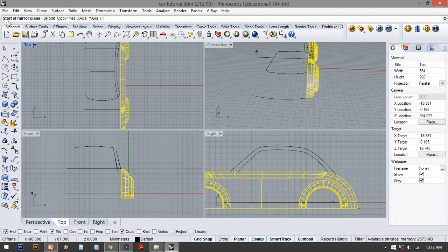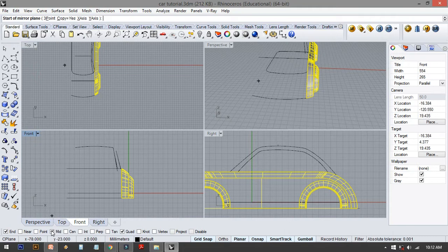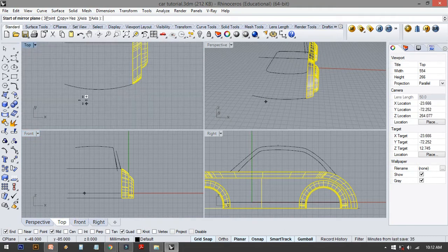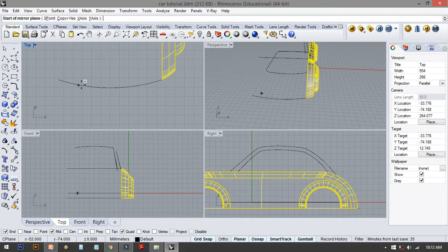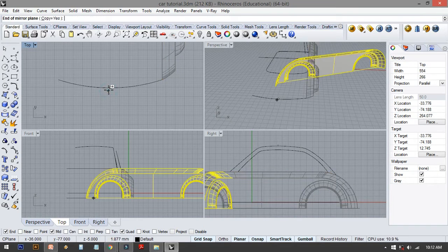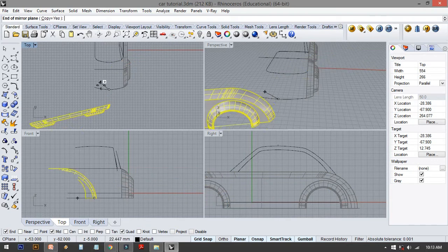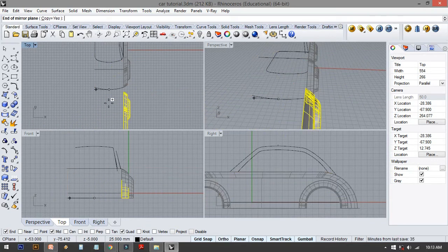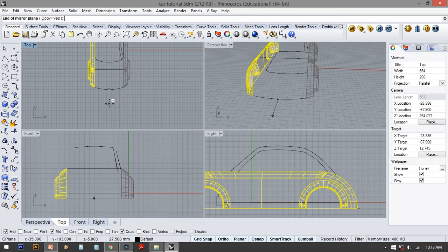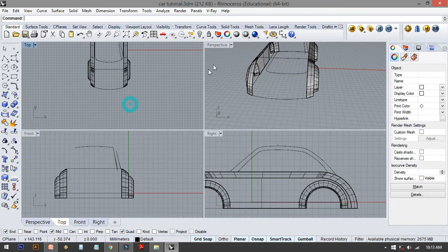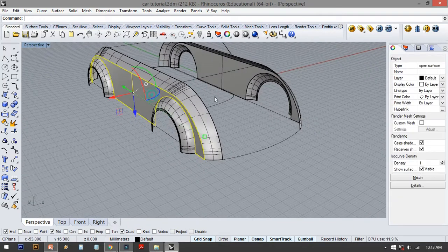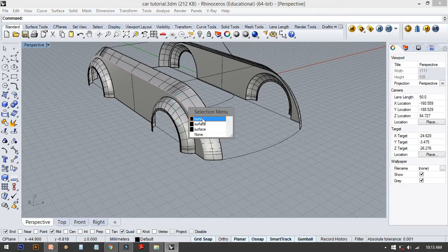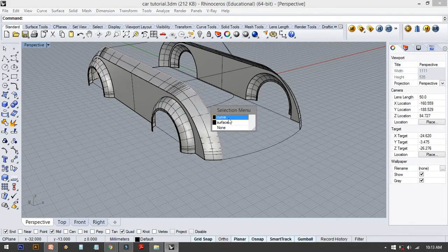Click on it, and then it will ask for the start of mirror plane. This is where the Mid is going to work. So we just drag the curve until it catches at the mid, see? Mid. So the start of mirror plane is from the mid. Then press shift while you're moving it, so it will capture like this, and then just click. There you go. So you already mirrored the object, together with the curve. See the curve here, together with the curve. Why is it so important?